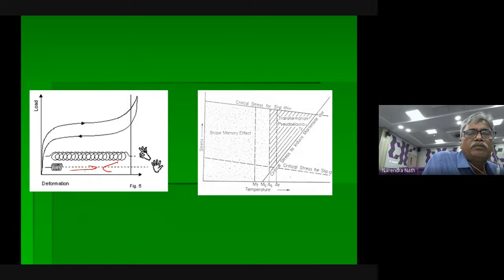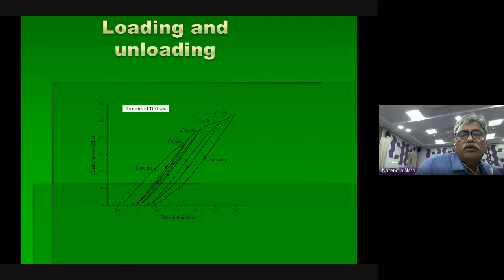Like this, if you do n number of times and return it back, you should come back to the original position. Suppose with time, if it stops here only, and with time this increases more, then that much residual stress is there. Then it is not usable. Say this spring is rated for 10,000 cycles; up to 10,000 cycles, it should not show any residual stress. If it shows, we have to replace it or something is wrong. So this is the loading and unloading taking place.